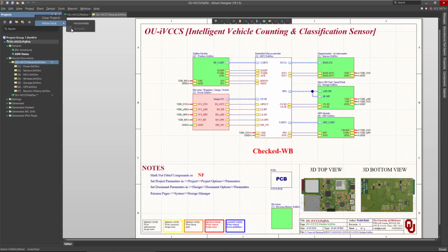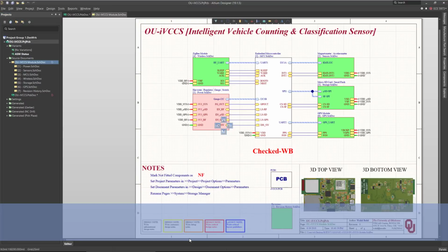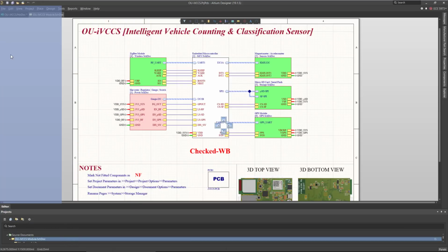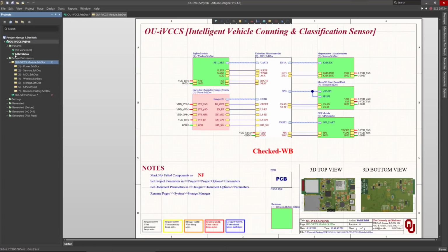Now it's vertical, and the only way to dock this is vertical. So if you activate horizontal docking, basically if you drag, let's go to here for instance, drop, and it's docked now horizontally. If you click on it again and drag it and move to the left side, leave it, and now it's docked vertically. You can also dock it to the right side or left side, top and bottom, based on the settings you select in here.